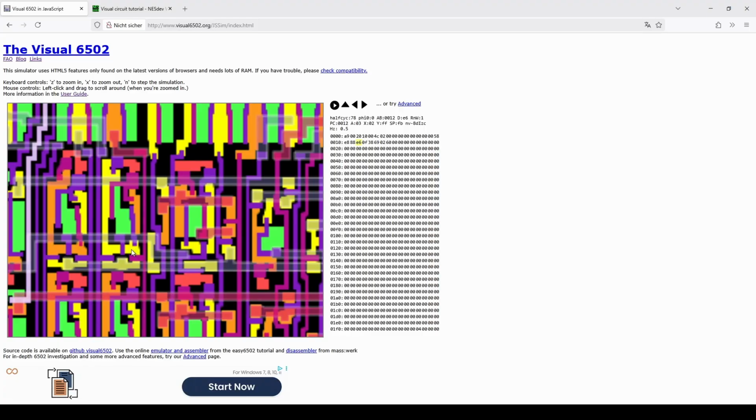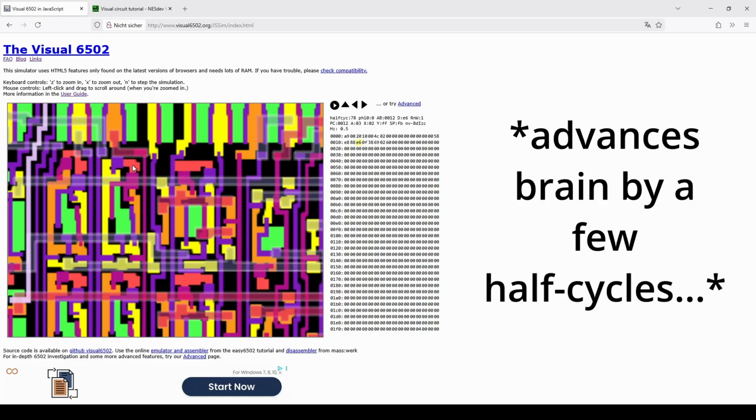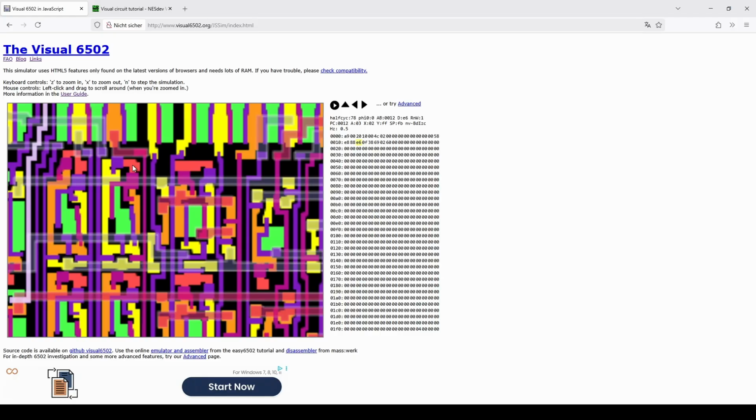So this drains, I would guess, to ground via the special bus, which causes this transistor no longer to conduct, which then means that this can no longer go to ground, so it becomes orange, right? It becomes a 1 basically, which then means it powers this again, which has no effect on the plus 5 volts getting here, but it does have an effect upon the output of this inverter, which will now no longer let current through. Sorry. Which will now let current through.